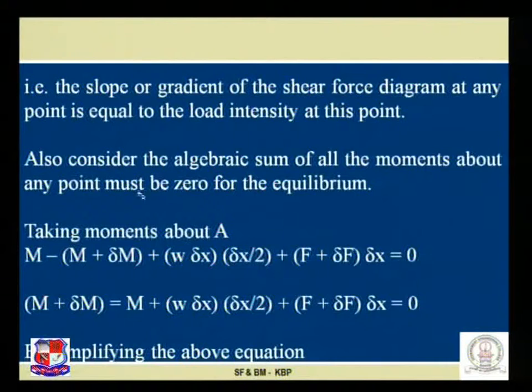That is, the slope or gradient of the shear force diagram at any point is equal to the load intensity at this particular point. I will repeat these words once again, which have a significance.